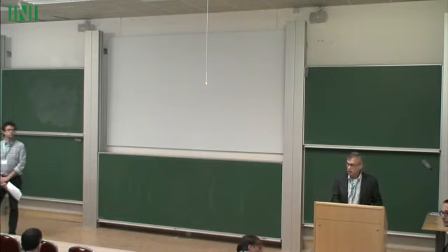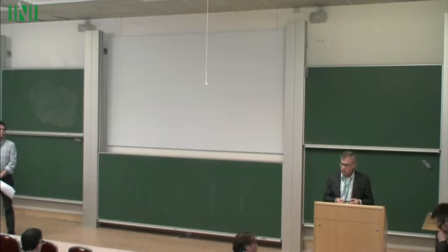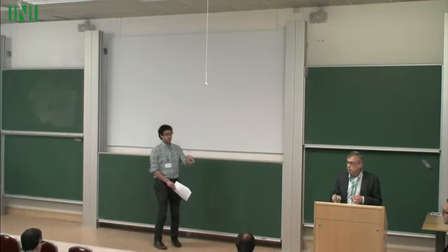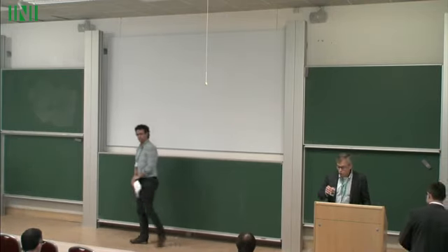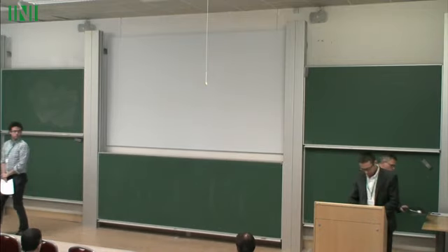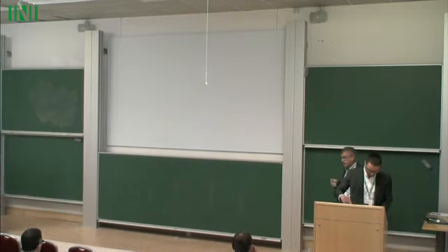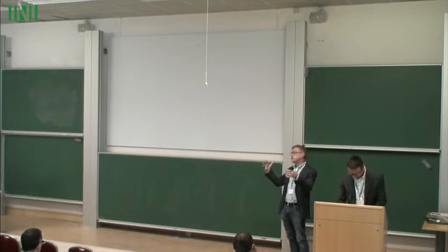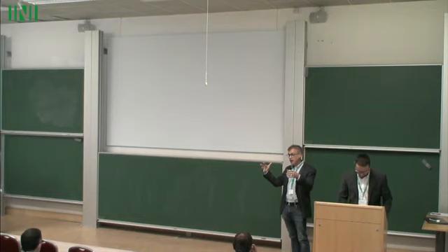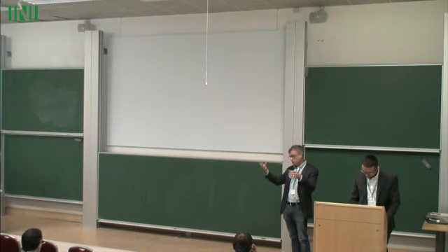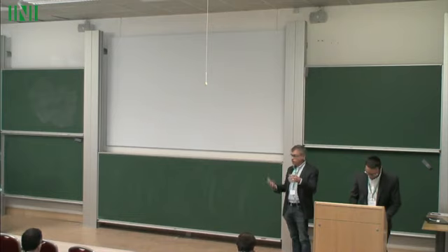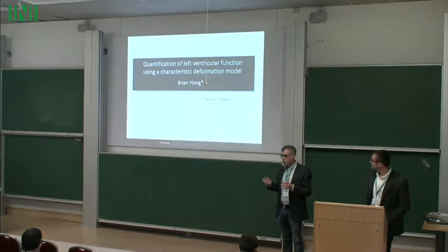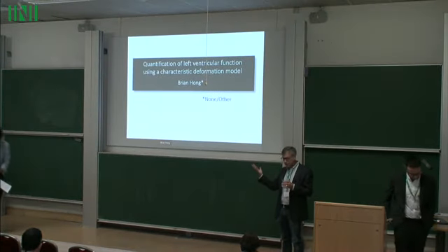You showed the last simulation of flow dynamics. So you say that the simulation was purely fluid driven. Do you have an electromechanical model at all? Or can you elaborate on that? So it's a fluid structure interaction simulation. So there's a mechanics model. Mechanics model in that particular case is a version of the Guccione model. And then there's an active tension model. We're using in this case an additive stress splitting. There's not any electromechanics yet.